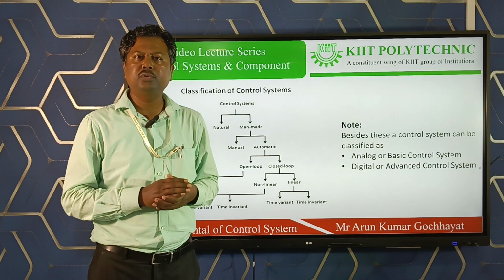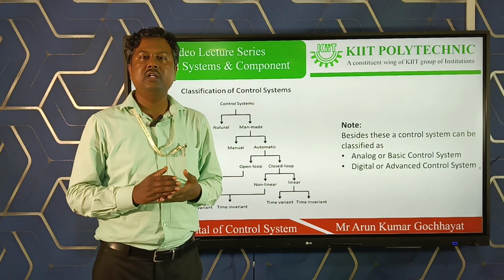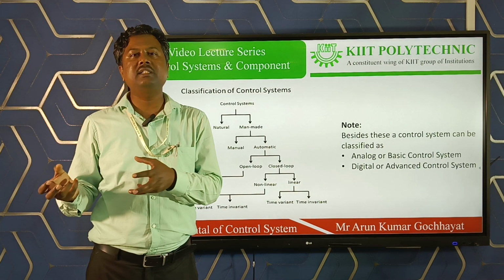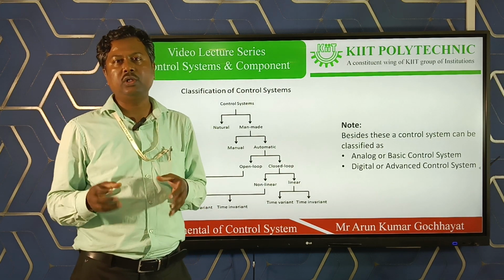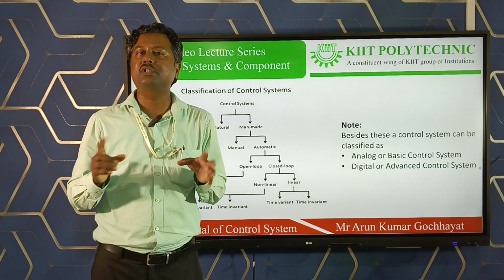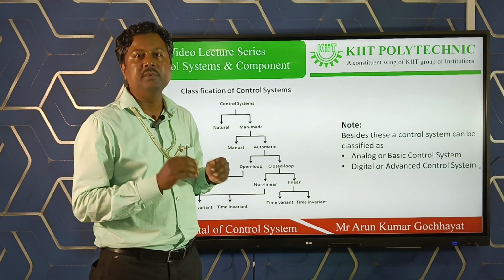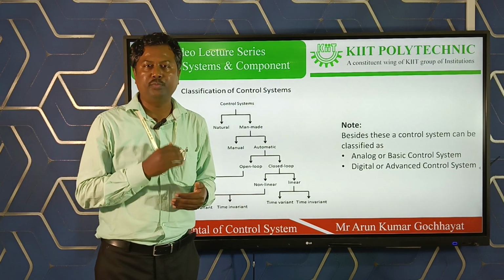As per the principle of superposition, the output of a control system for a simultaneous application of two or more inputs becomes equal to the sum of the individual outputs, if those multiple inputs are applied to the control system separately. That is the principle of superposition.